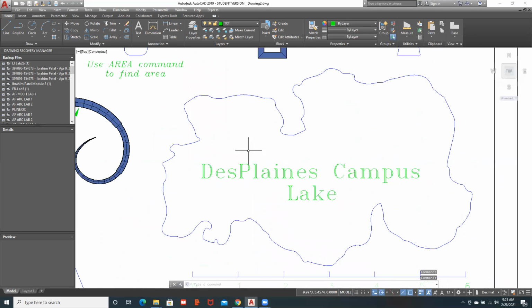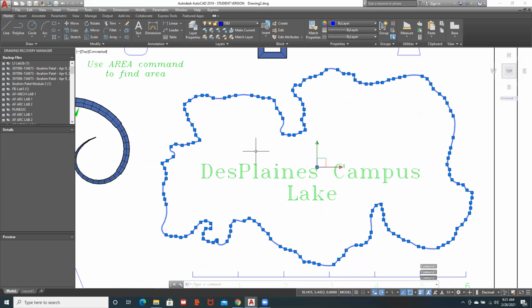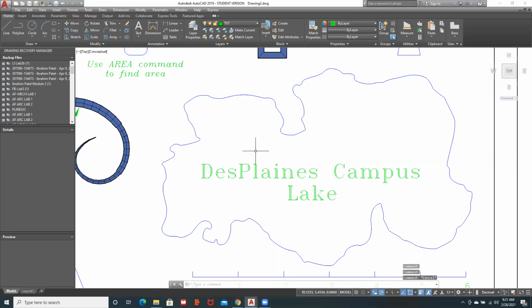Mapping, okay? As we go through and look at this exercise, this falls under Polylines with a command called the sketch command. And so if we sketch, the important thing in sketching is to read your command prompt and look at the increment value. If I type I for increment, I don't have my heads up drafting on. I can set the increment value very small. 0.5 is not good, 0.1 is pretty decent. So we'll say 0.1, hit enter and accept that.